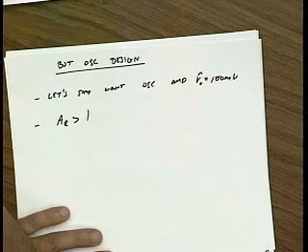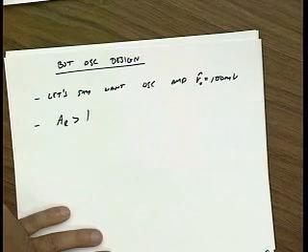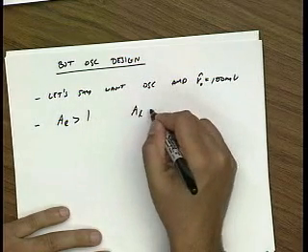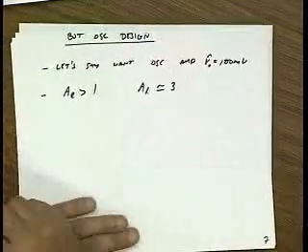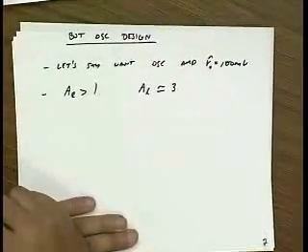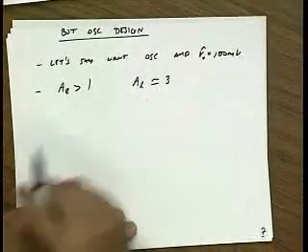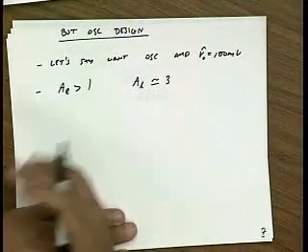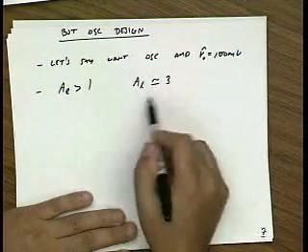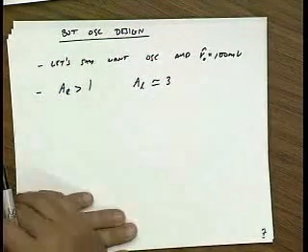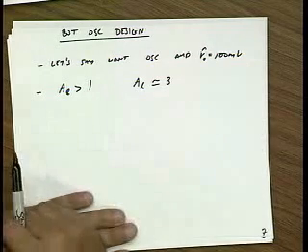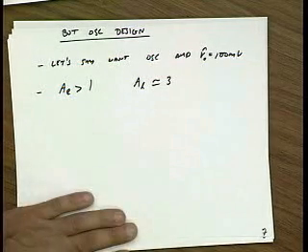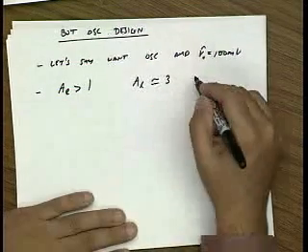An engineer says, well, the loop gain has to be bigger than 1 over process, over temperature, over everything. So why not make it, let's say 3, right? Seems like a very arbitrary choice. But in practice, you could say that 3 leads to a pretty good design. You could think of this as a starting point. I'll choose a loop gain of 3, and then I'll run some simulations and see how the performance changes if I change the initial loop gain. But this is a good starting point.